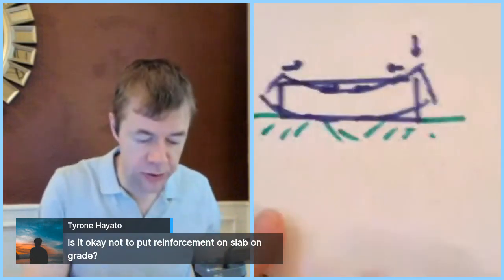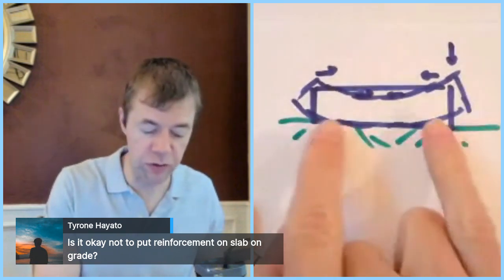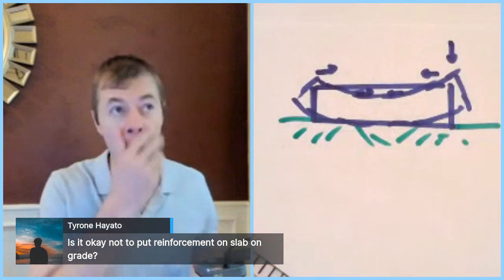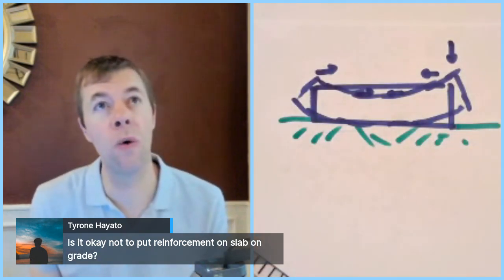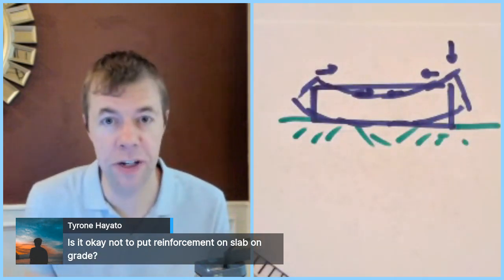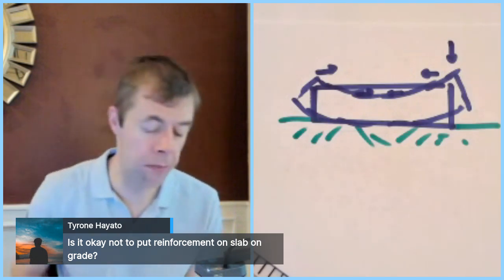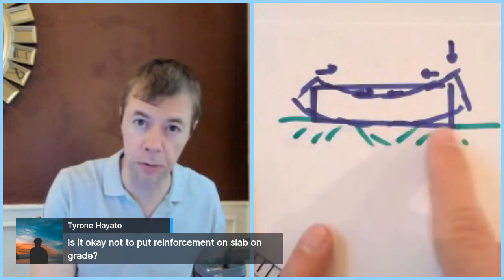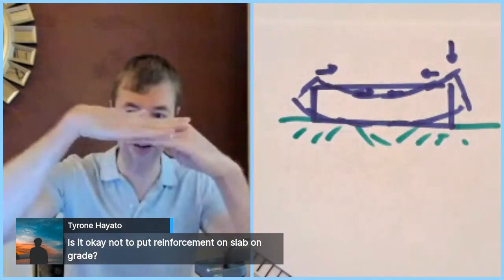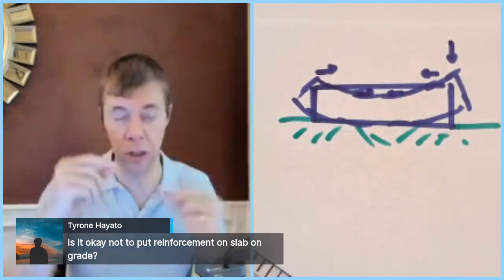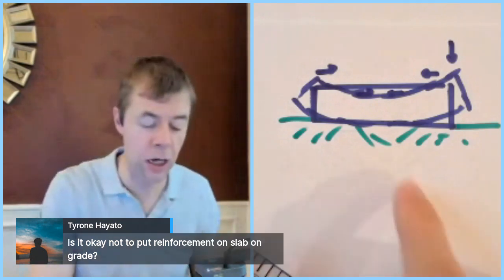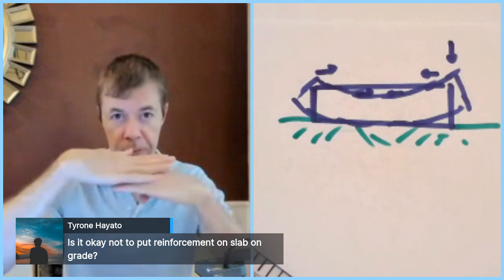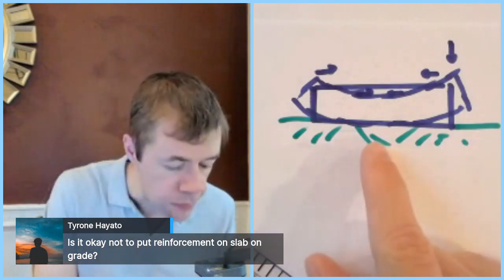One way is to make your slabs extremely small. And what's small? About less than 10 feet by 10 feet. You're going to want to put some kind of slip material on the bottom, some kind of double layer of plastic that the slab can slip on top of. You want to use pretty thick plastic, because when you place the concrete, you don't want to damage it. So you want it to be able to slip over the top of one another.